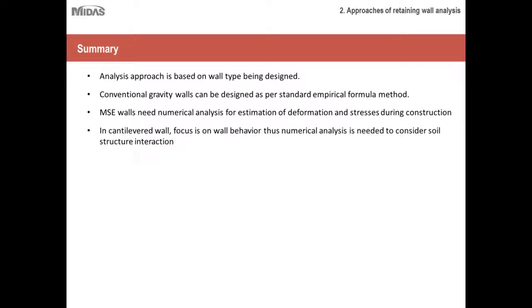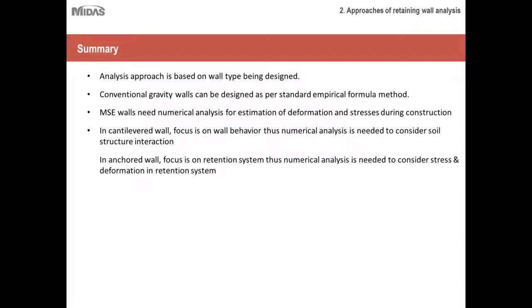In cantilevered wall, focus is on wall behavior, thus numerical analysis is needed to consider soil structure interaction. And in anchored wall, the focus is on the retention system, and thus numerical analysis is needed to consider stress and deformation in the retention system.